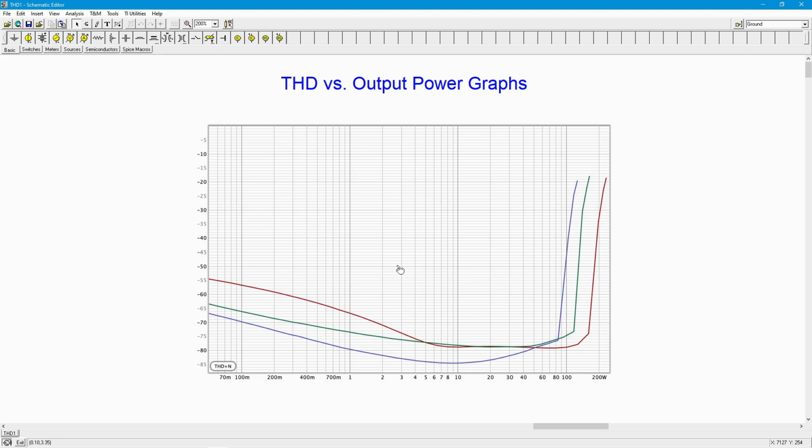If you took that circuit that we looked at a moment ago and you dropped the input to a millivolt instead of 20 millivolts, you're going to come up with a less distorted waveform. Just that simple. And it's going to gradually turn into a clipped signal. The part of the signal that was squished, that was fat, versus the other side that was really pointy, eventually that fat part's going to start clipping. It'll be obvious where it limits. So that's what you'd probably see for a Class A.